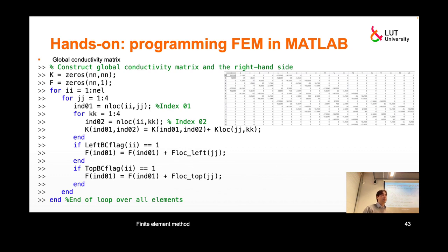Okay, so this is maybe the most important thing, how we combine local matrices into global. So this is kind of where the magic of the method goes, because we only need to define things for one element, and we need to explain somehow to the system how elements are connected, and then it will be able to solve for all elements. And this is exactly the way how we describe how those elements are connected in terms of the stiffness matrix and this right-hand side of the equation.